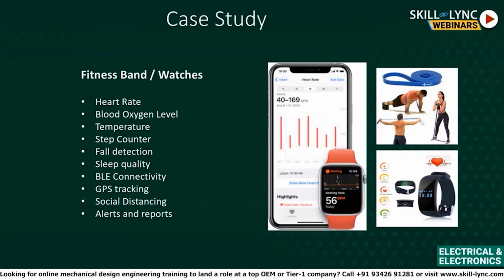This is not related to only acquiring data and displaying, because we have a lot of other processes, a lot of other sensors. We need to manage it efficiently. So instead of reading continuously, we will read whenever we want to read, and we will start the conversion. For that, we can choose a sensor which has this feature, and then simply read the temperature whenever we want it.